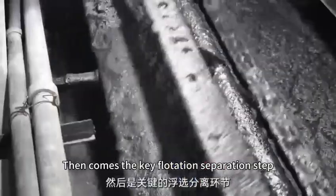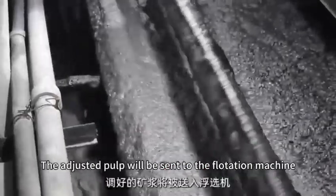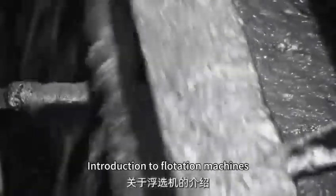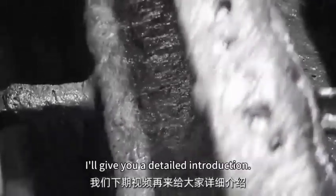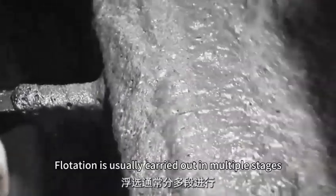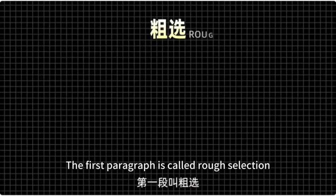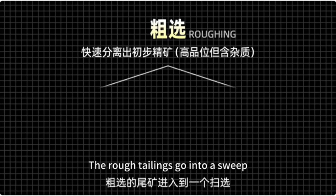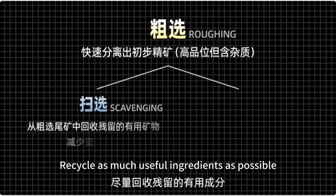Then comes the key flotation separation step. The adjusted pulp will be sent to the flotation machine. Introduction to the flotation machine: in our next video, I'll give you a detailed introduction. To increase collection rates, flotation is usually carried out in multiple stages. The first stage is called roughing, to quickly capture most useful minerals. The rough tailings go into scavenging, to recycle as much useful material as possible.